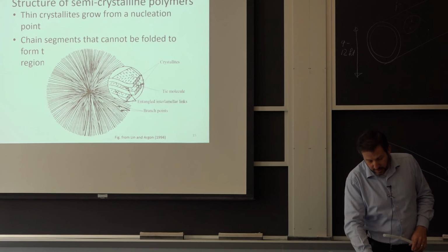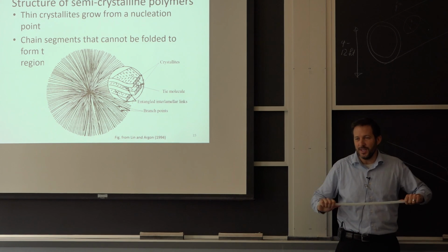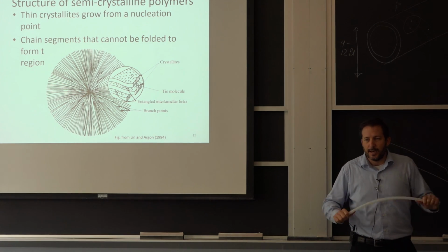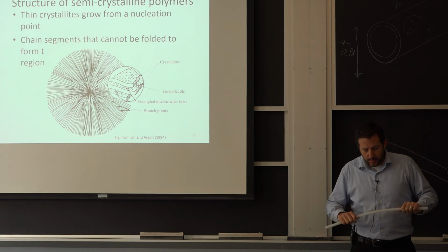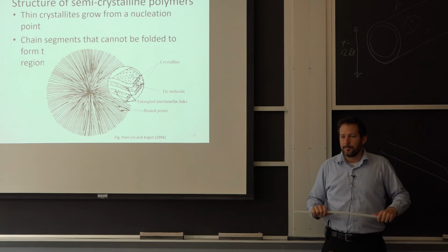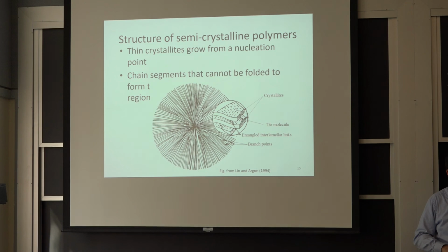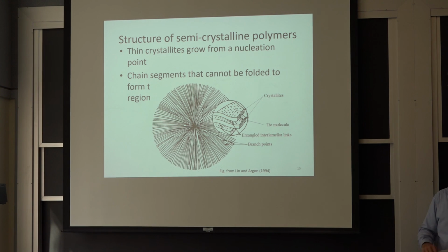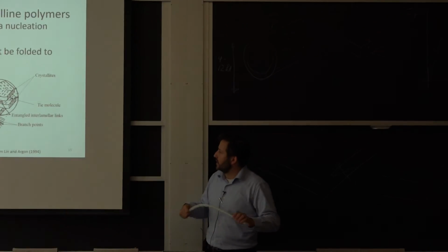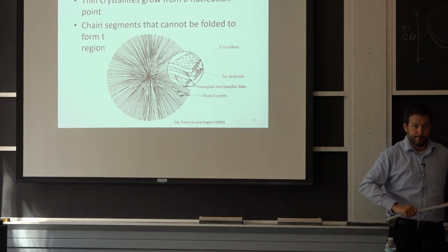Why do we care? It's affecting everything when you think about polymers. We've talked about the polymers when we talked about casting, that they have these spherulites, or they are essentially semi-crystalline. And what happens is everything we talk about, all that visco aspect, happens in the amorphous zone as opposed to in the small crystals.